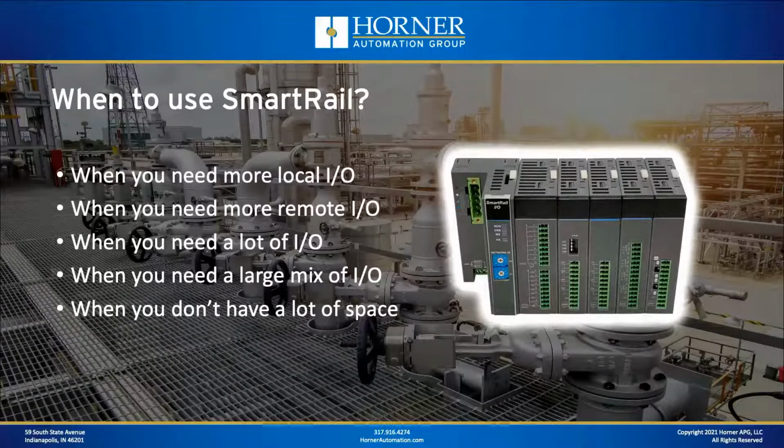Okay, so this is pretty much what Casey and I talked about just a minute ago. When to use SmartRail. When you need more local I/O. In other words, I/O in the same cabinet. We need more remote I/O, I/O that's distributed around. When you need a lot of I/O, you can get some pretty dense amount of I/O with SmartRail. When you need a large mix, the modular nature of SmartRail allows it to support mixes of I/O types very well. And when you don't have a lot of space, it's very compact, as Casey mentioned. So lots of situations when you might want to use SmartRail, and CsCAN SmartRail is an excellent choice from a networking standpoint.